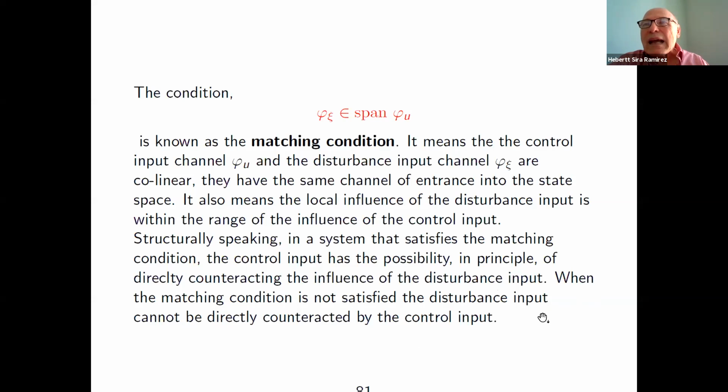You have a zero dynamics associated with that output, which is n-1 dimensional. Everything that's affecting your system will be there probably. And if it is there, then it affects your ideal sliding dynamics. When you manage to control your system to the surface, the dynamics in that manifold is being affected by the disturbance when you don't have the matching condition.